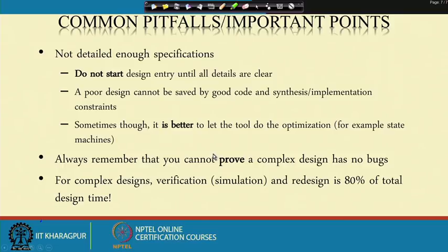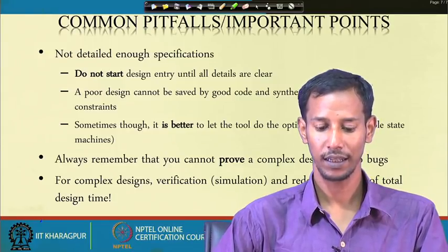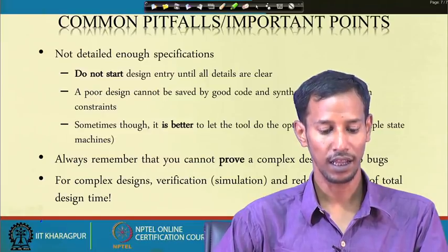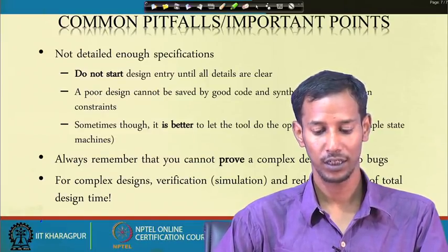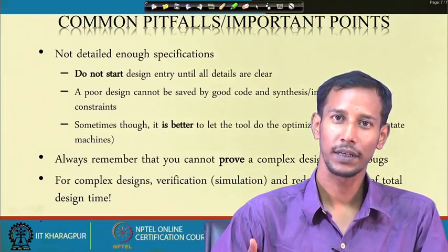The common pitfalls, or important points to keep in mind: not a detailed enough specification. Do not start design entry until all details are clear. A poor design cannot be saved by good code and synthesis implementation constraints. Sometimes it is better to let the tool do the optimization, that means manual optimization is not always better.